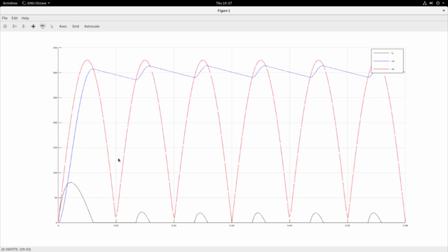In this way you can probe various voltages and currents in the circuit, and you can get the ratings of the various devices even before you put in generic devices or the actual components. And if you are thinking of innovating circuits, coming up with different circuit topologies for the same set of equations, it is possible because you are doing equation-based modeling. Of course, I will leave you to explore this possibility and get more insight into it.